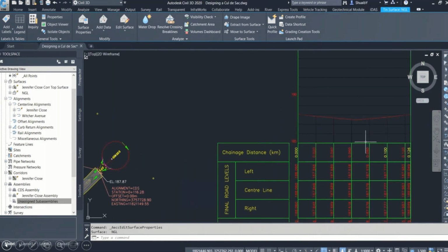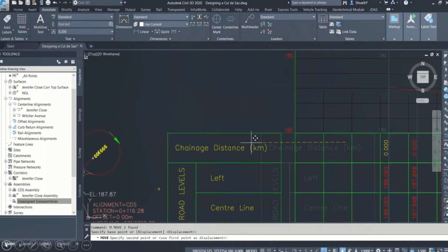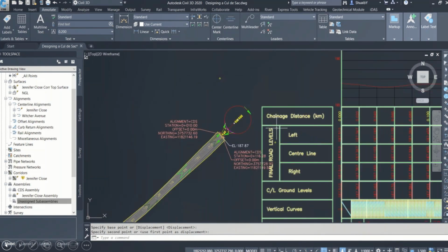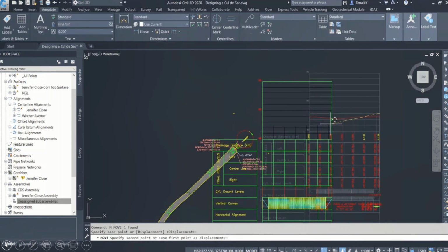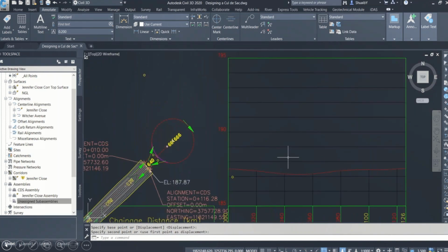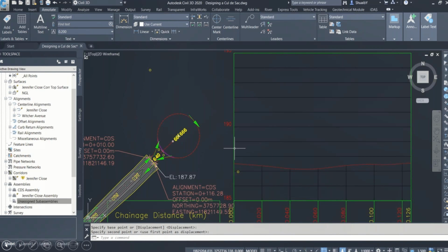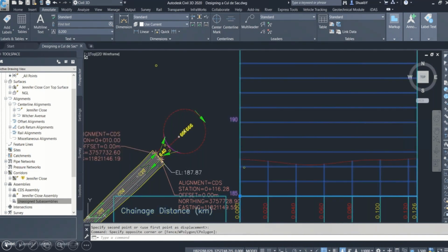And now we're going to use those stations that we actually generated to get us tied in correctly. So let's bring it a bit closer. It looks a bit messy, but it'll be easier for you guys to follow on your side. Let's position this a little bit down. Now we can use those start and end elevations and stations that we've got on the long section. How we do that is we're going to use the cul-de-sac again as a guide, because that's going to be our alignment reference points, so the elevations and that.